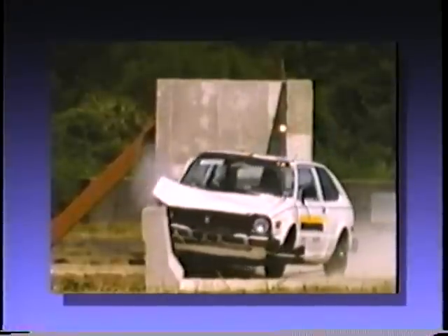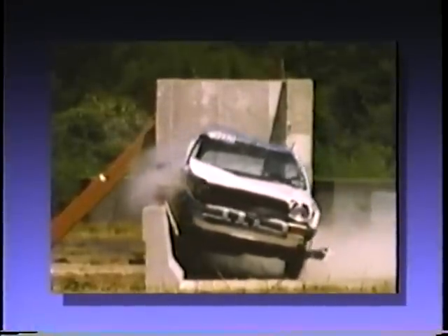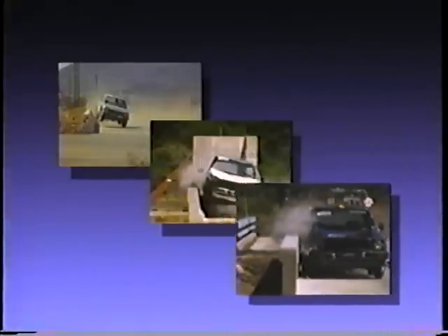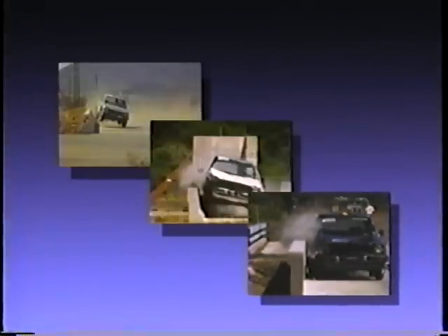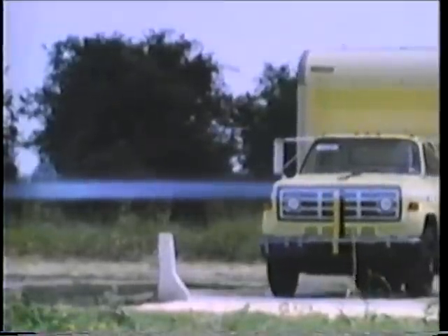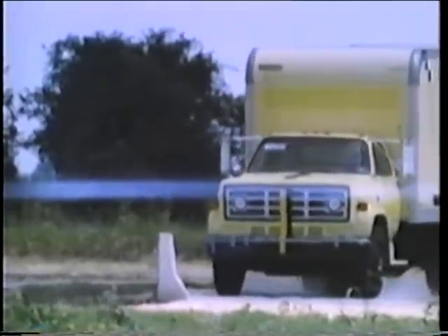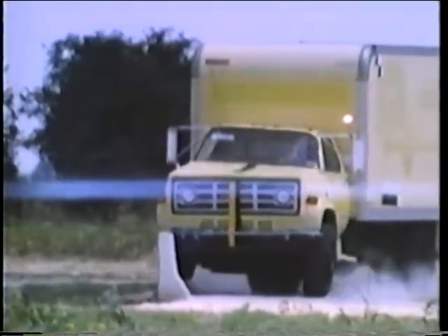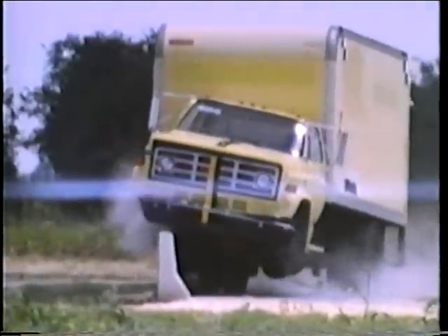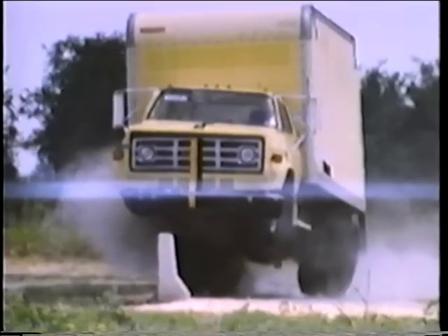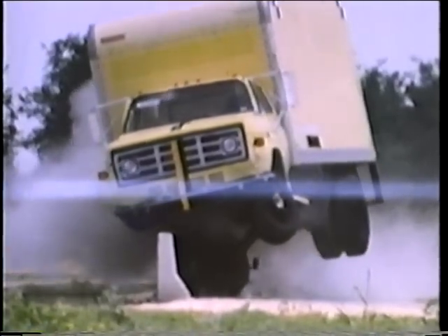The vehicle stability for the shaped barriers is not as good as for the vertical wall. The vertical wall has the best roll stability characteristics, but it causes the most wheel damage, which can result in the vehicle re-entering the roadway. Improved vehicle stability is even more important in impacts with trucks. Although the shaped barriers contained heavy trucks, the vertical barrier keeps the trucks upright and more stable.